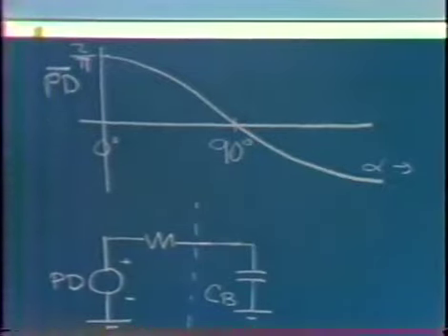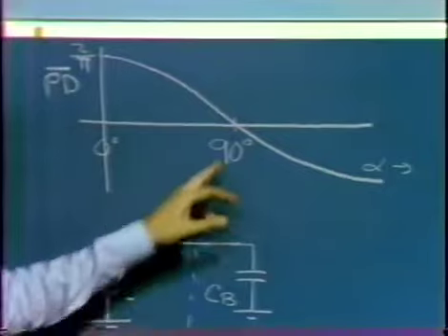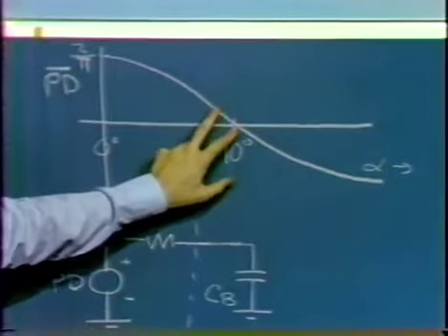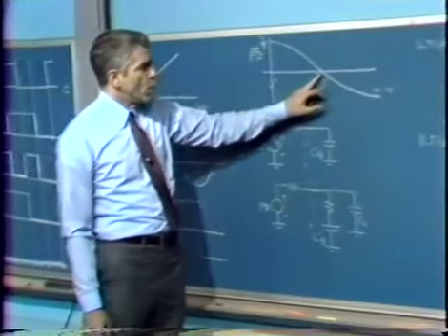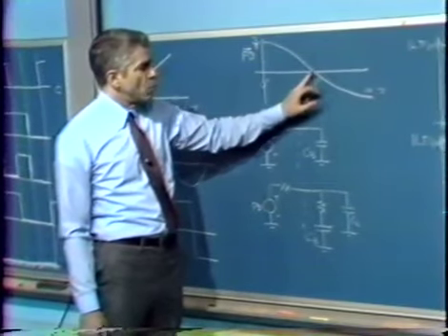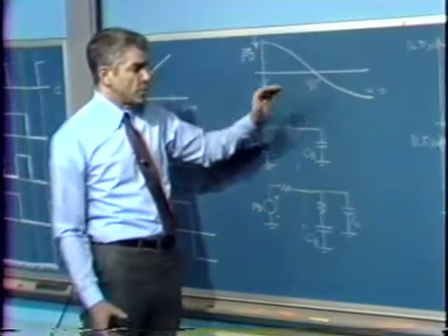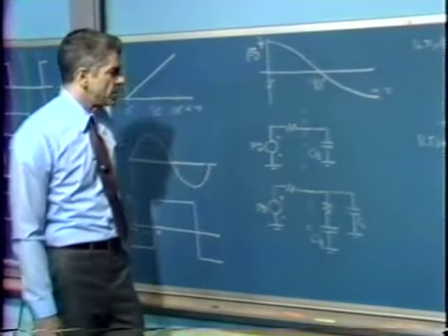Again, this is cyclical, it repeats. We get points of positive feedback or points of negative feedback displaced from each other by 180 degrees of relative phase shift. Only one of these sets of points will be a stable equilibrium for the loop. The other one, of course, will be a positive feedback point.